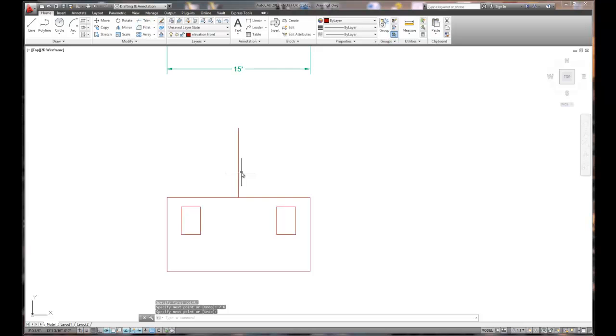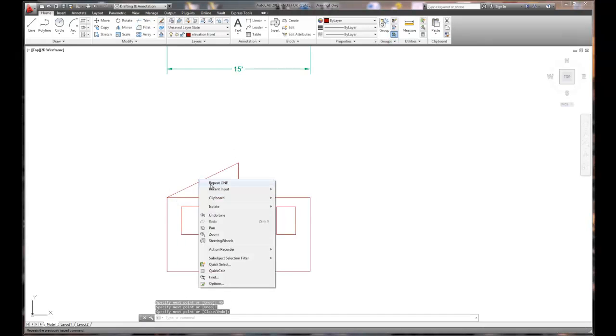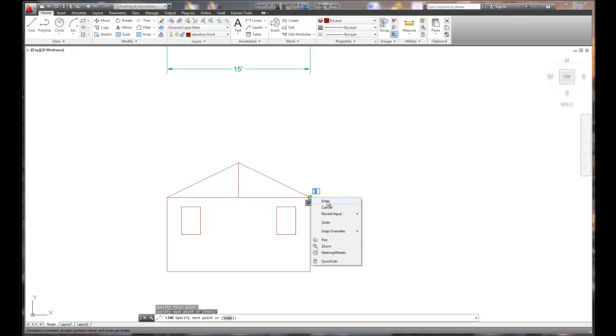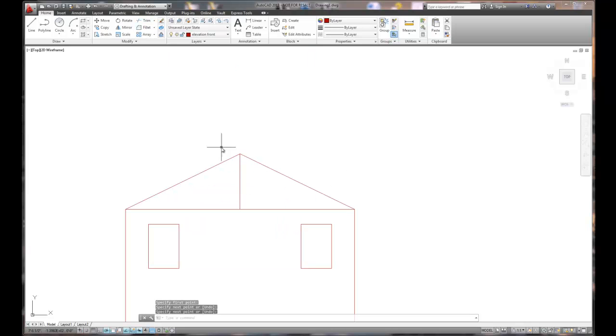For that roof pitch? Well, that would be a 12-12, wouldn't it? Because a 12-12 would be 45 degrees, so that would be 7.5. So we would want to be a quarter of that. Okay. So, you go, if you want, you can go 7.5 times 6. That's 45 inches. And so we should be 45 inches off the top. And so from there, what we'll do is we'll create, as I just did, draw in the actual roof line,